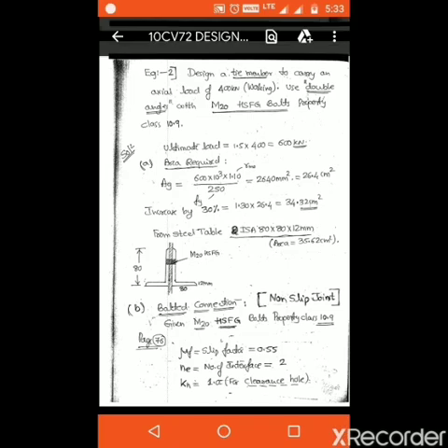Now write down the figure for the double angle section. It is also given in the steel book, so whatever figure is given in the steel book, we should write the same figure. The first step is to calculate the area and select the suitable section. After selecting the suitable section, the next step is the connection, whether it is bolted connection or welded connection.